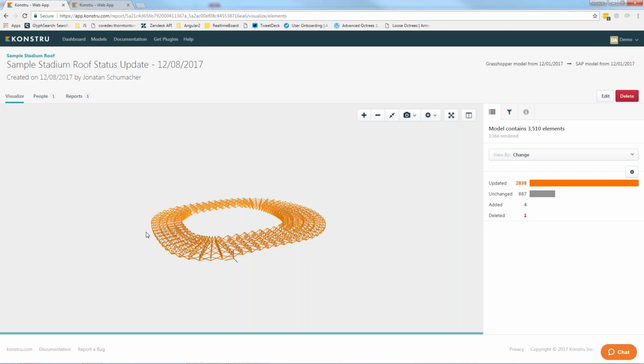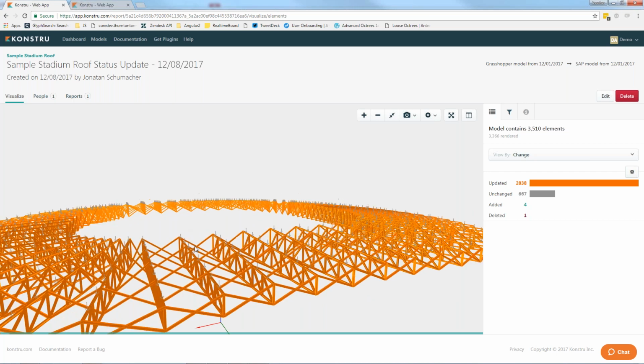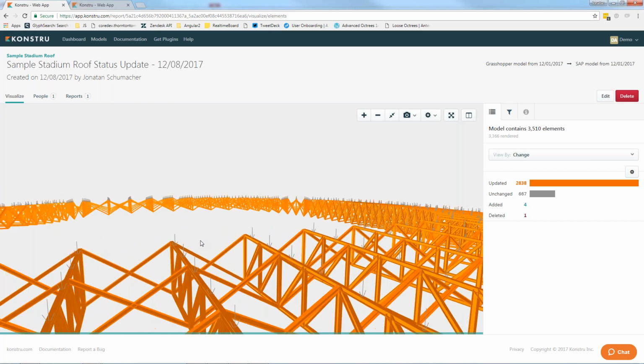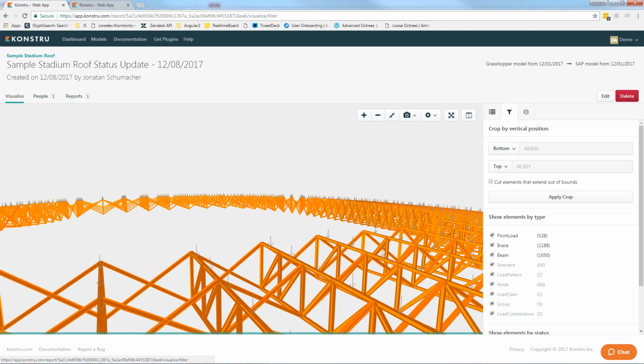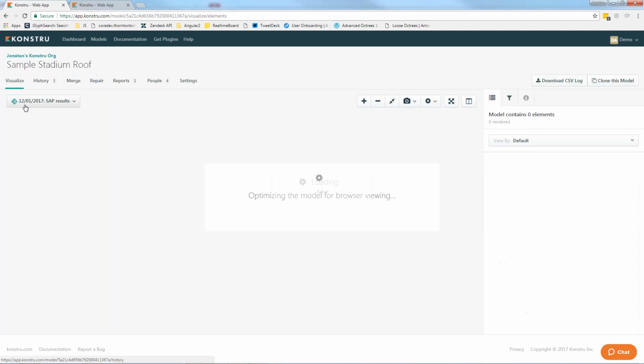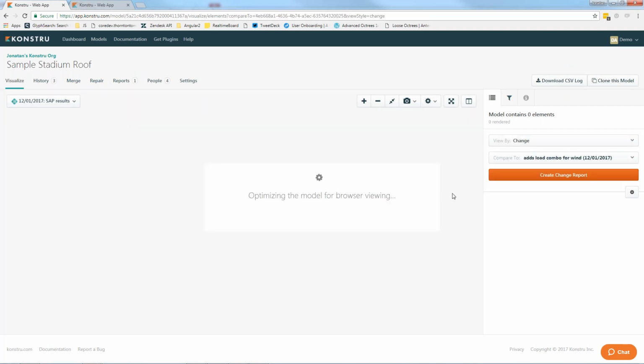Since load cases are a very abstract element because they're not really an element that exists in your model as a physical object, we don't visualize them, but you saw them in the tab. So you see them by names, and you can actually select them even from the sidebar where you can select all the elements that have been added, but there's no physical element representing them. What we do represent are point loads, line loads, area loads, and all of that.